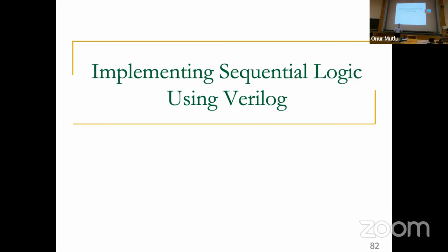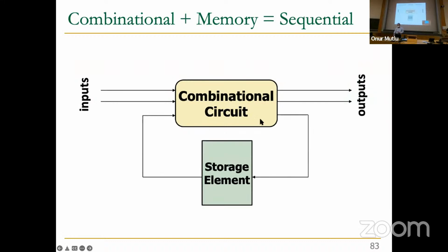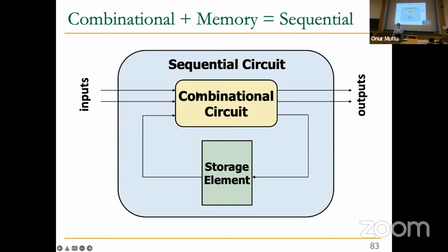Okay, so let's now jump into describing sequential logic, because clearly you cannot build systems without sequential logic, and sequential logic is certainly interesting, right? And Verilog provides a specialized way of specifying sequential logic also. So, okay, what is sequential logic? Just to jog your memory, you have some combinational circuit that evaluates the outputs as well as the next state, and then you have a storage element that stores the state, potentially the outputs as well, and then you remember that information about what you have computed in the past to determine something in the future also. So that's your sequential circuit basically.